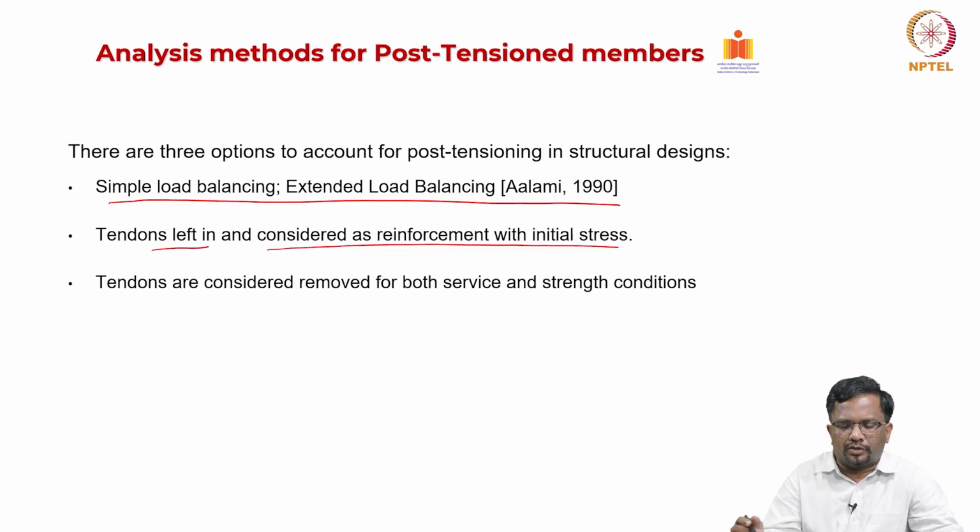The third approach is that you do not consider the tendons at all in the design. The tendons are not considered for either service or strength. You basically design it like an RC slab, which is not really correct, and this will lead to a very unconservative design.